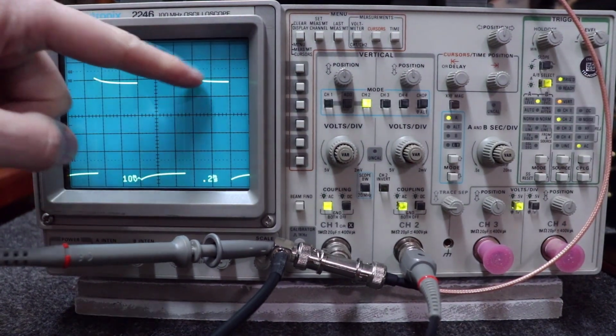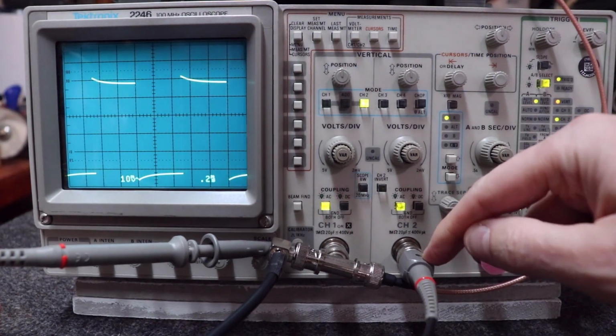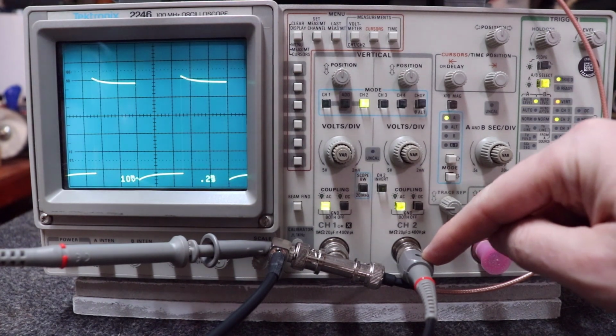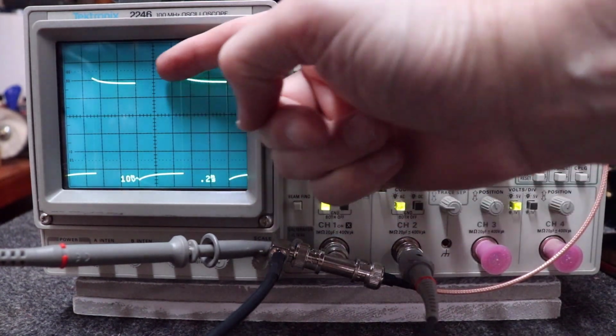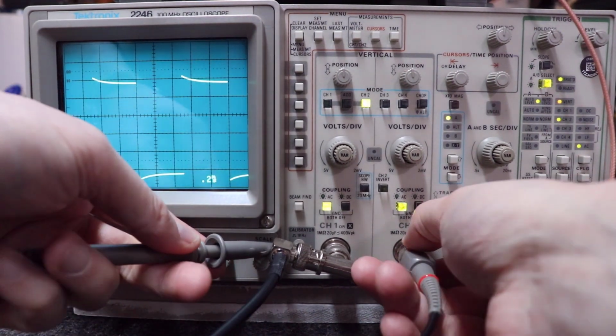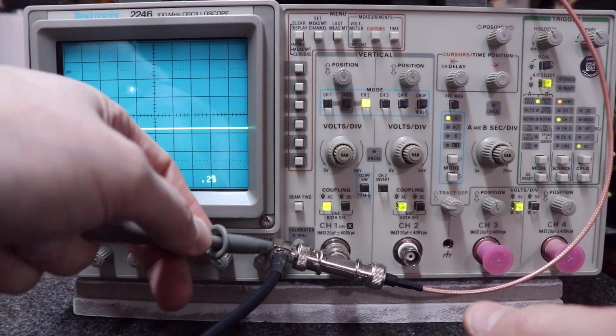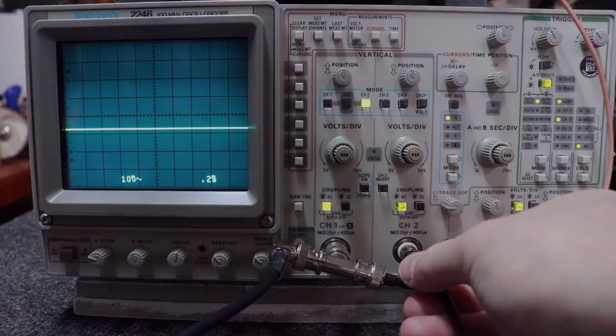Okay, and if you'll notice here, I've got this little swoop up on my signal. I could use a little bitty screwdriver to adjust this scope probe right here. It's just a little trimmer capacitor inside of there, and you would get that signal as flat as could be. And what you're really doing is calibrating your scope because it's putting out a known signal right there. That's what it's used for.